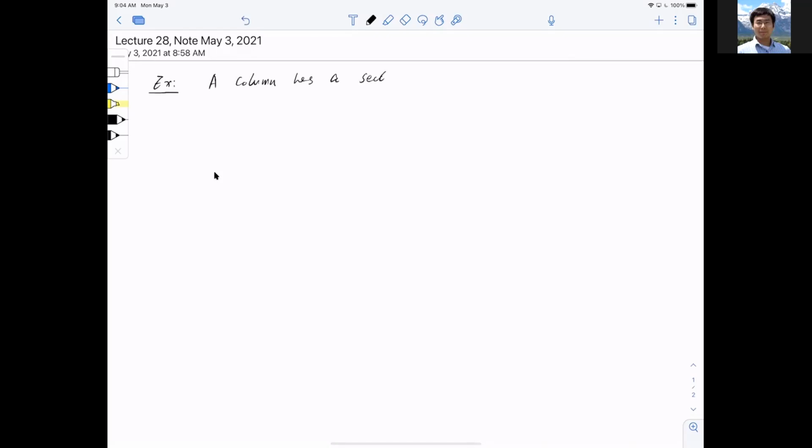shown below, okay? And I will show you that it is a very typical rectangular section, okay? And the concrete to be used for this section is f'c equal to 5 ksi, okay? Then the grade 60 steel, meaning yield strength of the steel 60 ksi, okay?